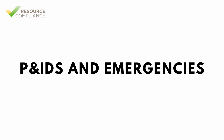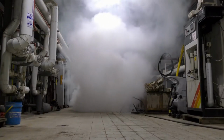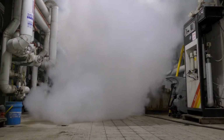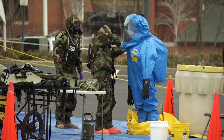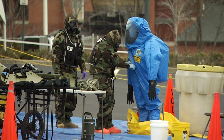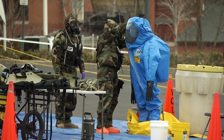Preparation is critical for emergency readiness. At a chemical facility, an accurate P&ID is an indispensable tool to aid hazmat responders in making decisions during a crisis. With this in mind, P&IDs must be readily available to responders at all times. Often, chemical leaks can be stopped by closing a downstream isolation valve. The P&ID is an ideal resource to locate such a valve prior to hazmat team entry.